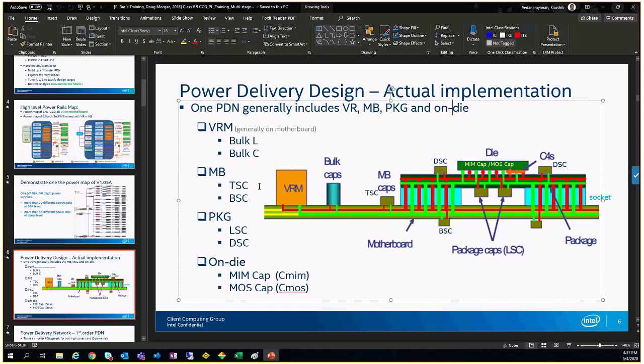That is handled by the PD team, the power delivery team, the board team. As a PI engineer, your job starts from the inductor. From the inductor till the die is your domain, where you will be doing most of the system work. Your job is to ensure you meet the power specs in this region. So we only use an LVR and RVR value, which the PDT will provide you with.